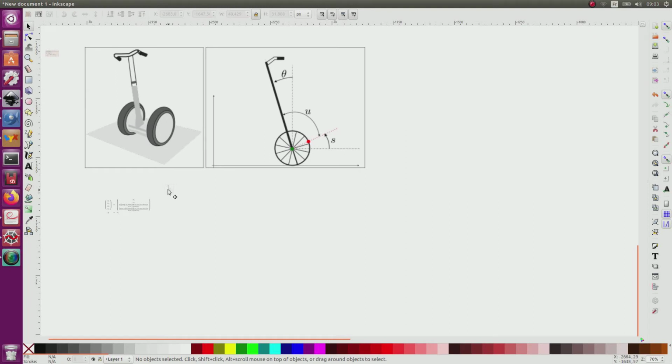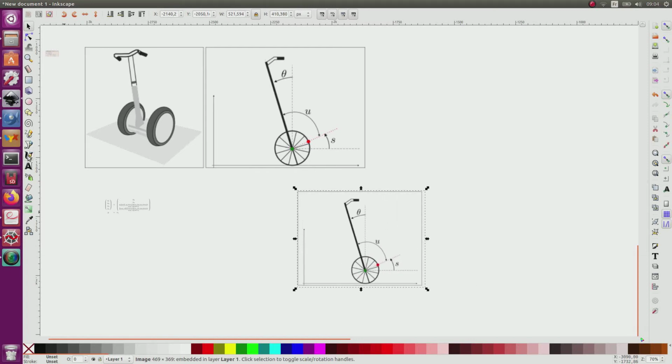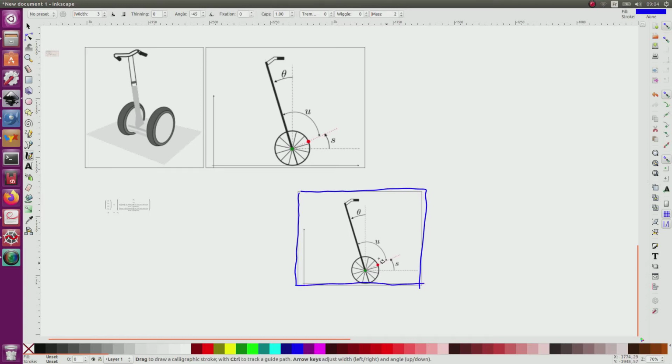So the system is represented here, and recall that we will first consider the planar version. The planar version is this system where you have the only input u corresponding to the torque that we can apply with a motor between the wheel and the body. The only thing we can measure corresponds to s. So it means that we'll need an observer to estimate theta.